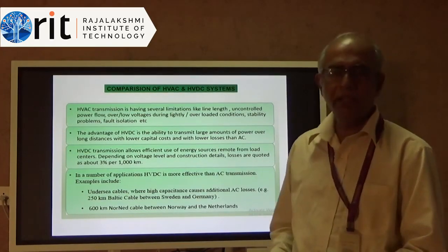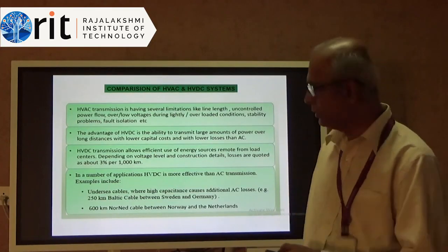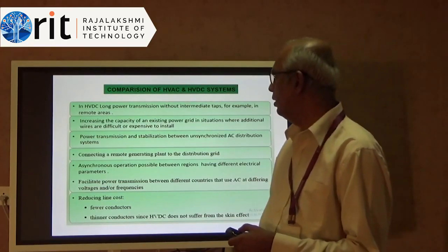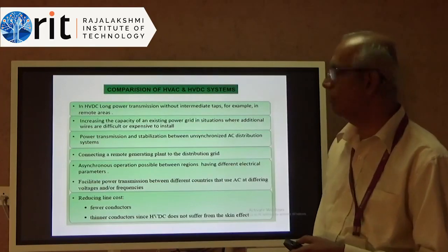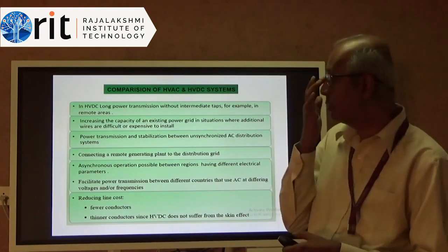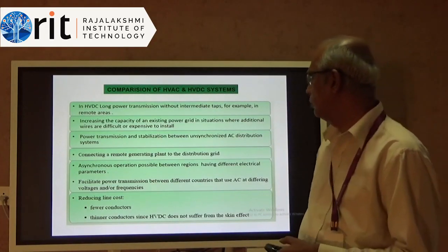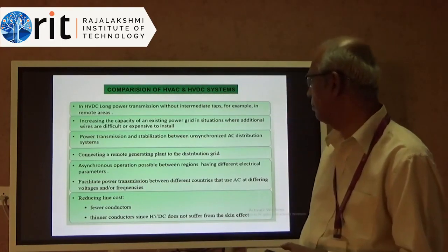And for example, country to country, if you want to have undersea cables, yes, it is possible with DC transmission, probably not so easy with AC transmission. In long HVDC power transmission without intermediate taps for connecting in remote areas, right? Even in remote load centers you can connect, because you have no difficulty on the amount of power which you can transmit, right? So that way you have many other advantages which accrue from DC transmission, connecting a remote generating plant to a distribution grid.